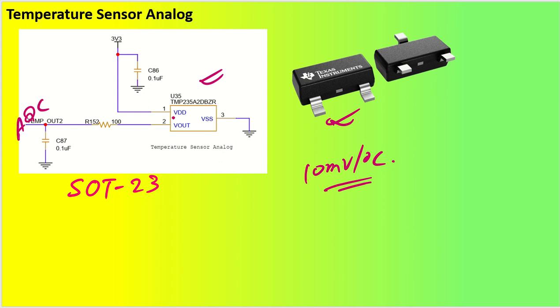You can send it directly to the ADC, which will be measuring the output. Simply give one voltage to this particular sensor, you have a ground pin, and the output pin can be taken directly. Similar to that, we have the LM35 also, which is a very popular IC. We have taken that example in a lot of our microcontroller sessions, so that one also you can take.